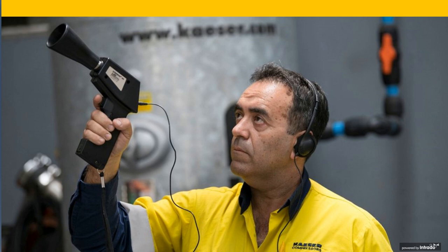There are auditors out there that can walk your plant, identify all of your leaks, tag these leaks, and then provide you with a report describing the estimated flow and cost of each of these leaks. And you can do those things yourselves if you procure the equipment and get some training. The best advice is to fix your largest leaks first.